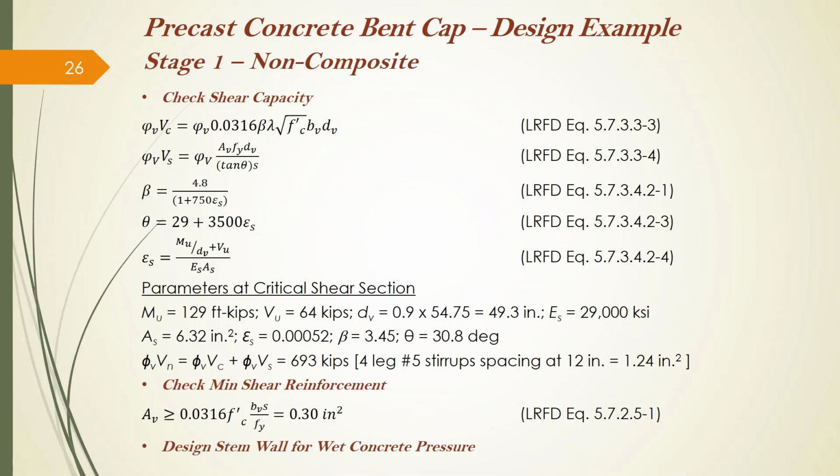For the non-composite section, we also need to go through the shear capacity and shear demand, and these are standard AASHTO LRFD equations. Again, with nominal shear reinforcement, the shear demand for this stage is met. Next slide, please.